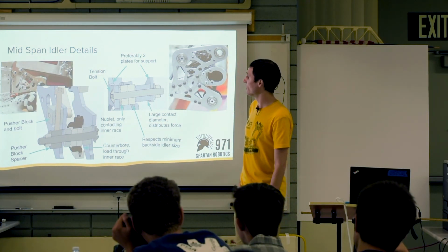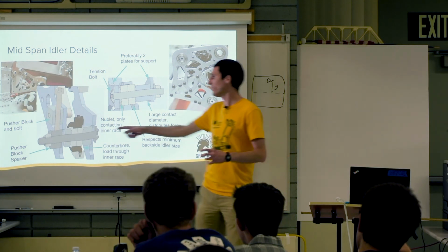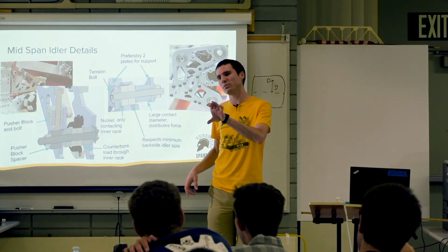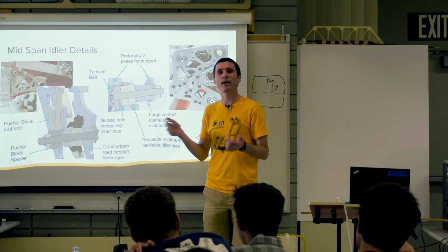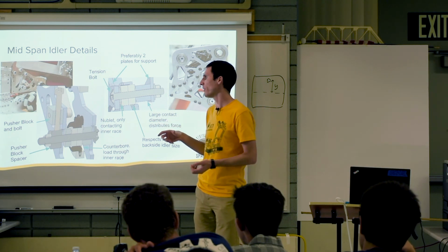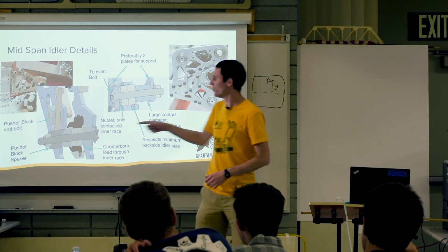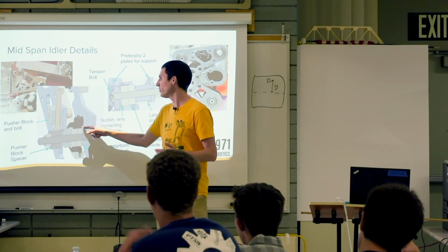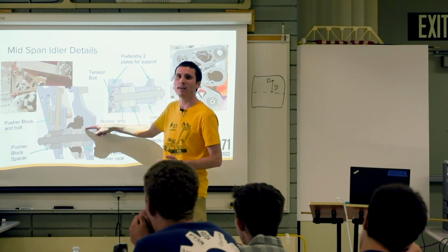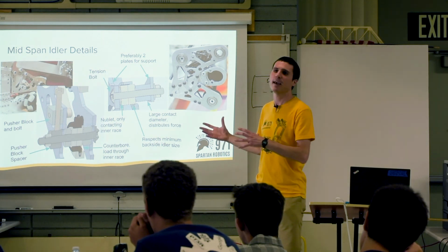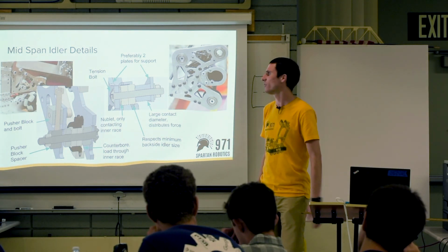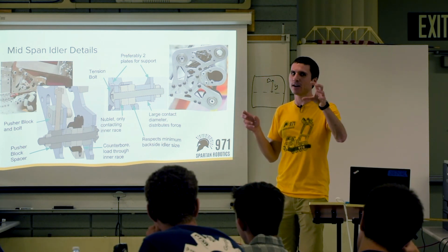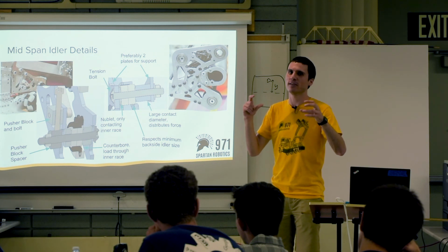And then another thing when you have bearings: this is our idler sprocket. We make these sprockets and use them all over the place. We basically took a sprocket, the hex sprocket, and bored out the middle to fit two 1/4-inch bearings in them. The sprocket is wider than the two bearings put together, so we end up putting this little pocket in the end of it. Can anyone think of why we'd want to put that pocket in the end of the sprocket? It's harder to machine, but it serves some functional purposes. Why would that be important? So let's think about it. We have a bearing that has the outer race and the inner race, and it has balls supporting the outer race and the inner race.